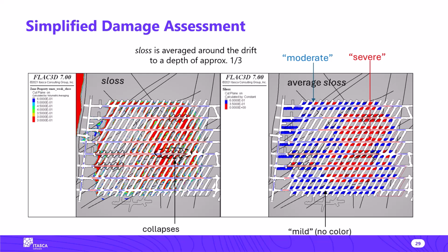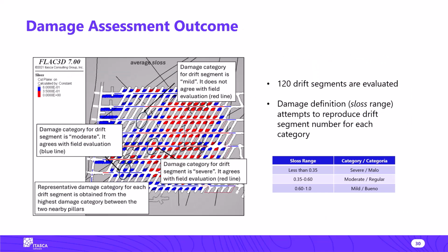Recall that zero damage means S-loss equals 1, with 0 being the post-peak residual, that is the maximum damage related to plastic strain. As mentioned previously, any calibration process is the best compromise between the information available and the interpretation of the variables of interest.